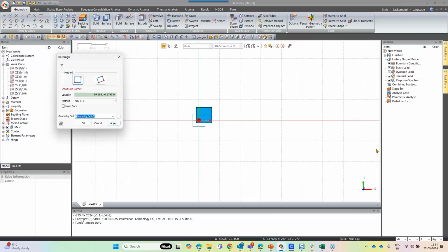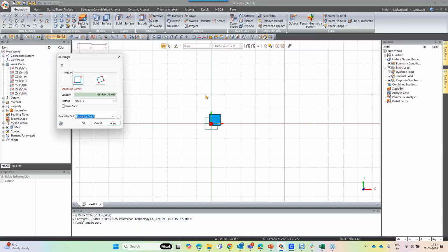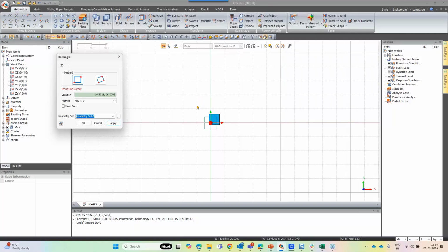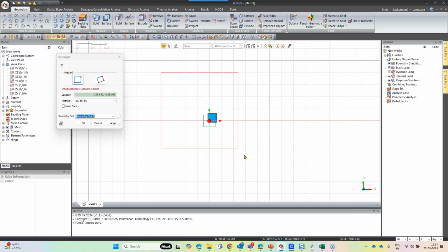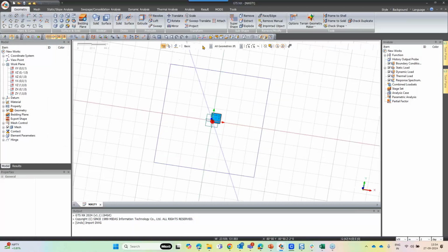So here we go. Each box is of 20-meter width by default in the software. You can change the grid size at any point of time. Let's assign at least 3 times the width on either side. So the width of the raft is 15 meters. So here it is 15, 20, 20, and 20. Or we can go with at least 60 meters on either side. So let's provide 4 on either side. Yeah, so this is the boundary of the soil layer.